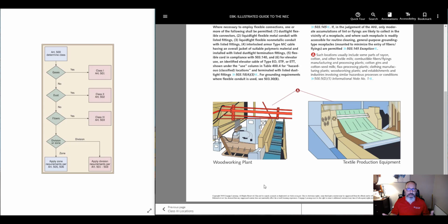I opened it up. We looked at the drives. Sure enough, there was a layer of carbon fiber dust on there. And being carbon fiber, it's conductive. So you have to look at that installation as a whole. And they weren't treating it as a hazardous classification. There was another situation where the carbon fiber dust went into telecom equipment and shorted out the telecom equipment because it was installed in that room, but they didn't think about it being utilized for carbon fiber, or maybe it was later on used for carbon fiber and it became conductive.